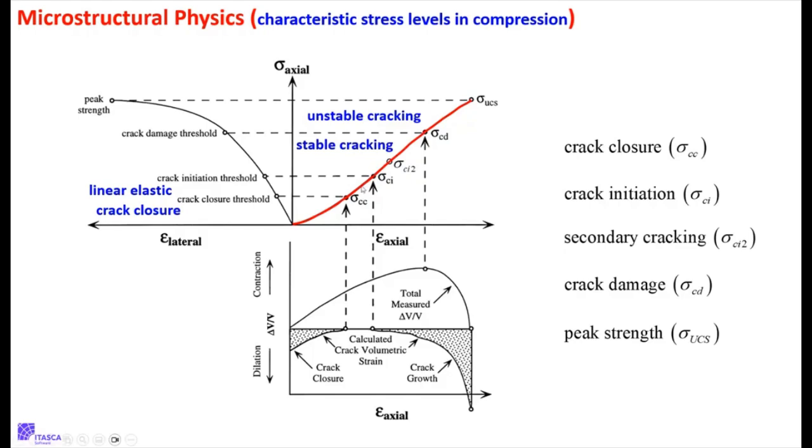And also, people who do super careful tests find that if you unload this thing in this region, it will not go back to exactly the same place that it was. So there's a little bit of cracking, but it's quite negligible. But at this point, look at this. Now suddenly it's bulging a lot compared to if it was elastic. That's attributed to cracks that are forming, a lot of them. And we call this point, when this starts happening quite a bit, crack initiation. So we got here, okay?